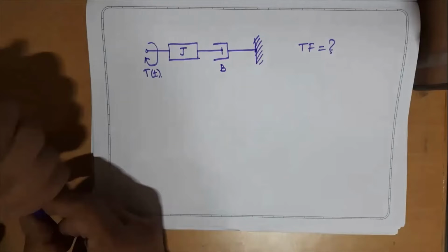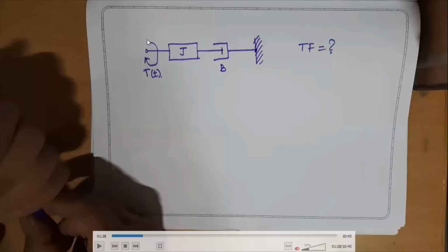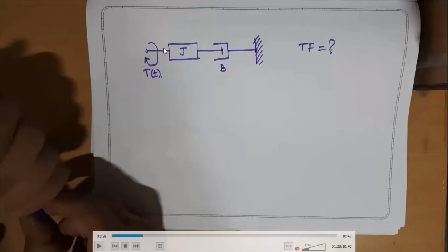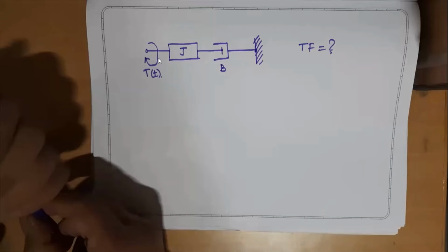The output variables are obviously the angular displacement for the given rotational force or torque. If you imagine this in a practical scenario, you have one shaft and one damper or a piston, then you have a moment of inertia block or a shaft. When you apply the rotating force to this shaft, there will be a displacement at this point. So let us call it theta of t.